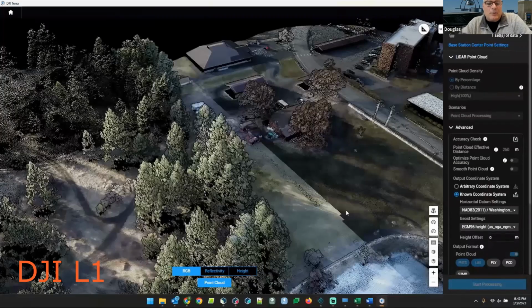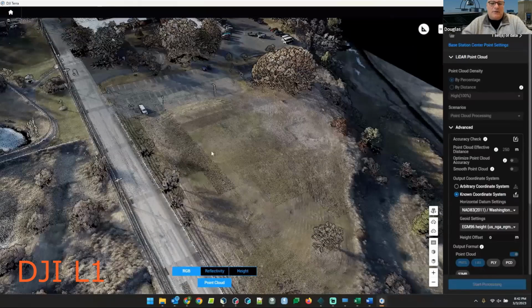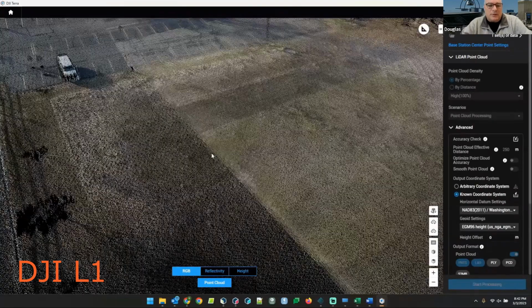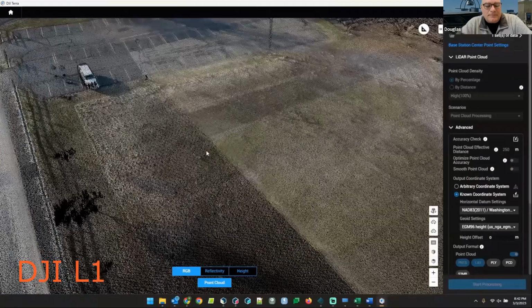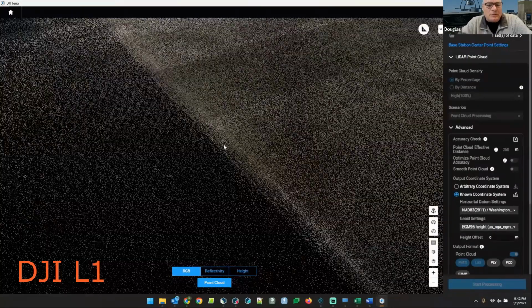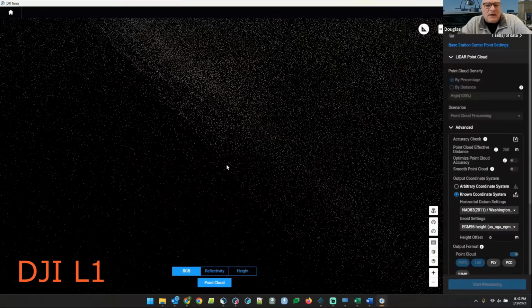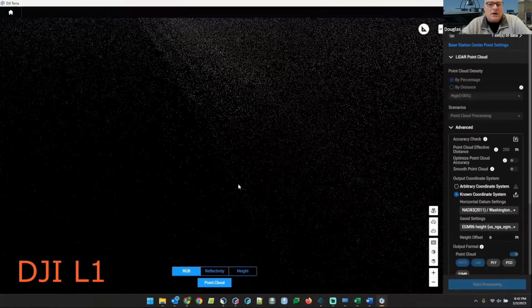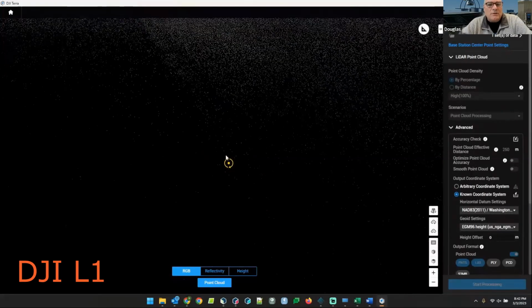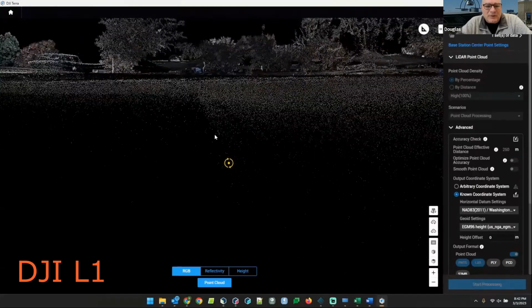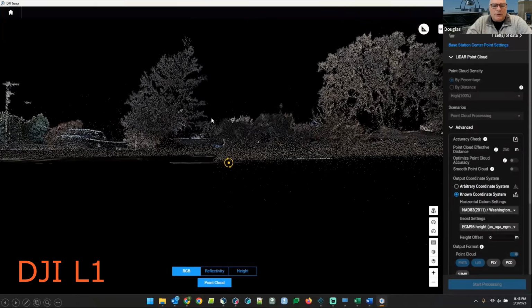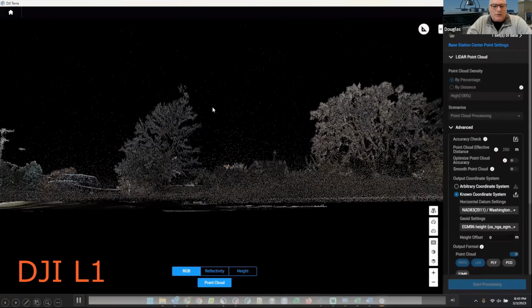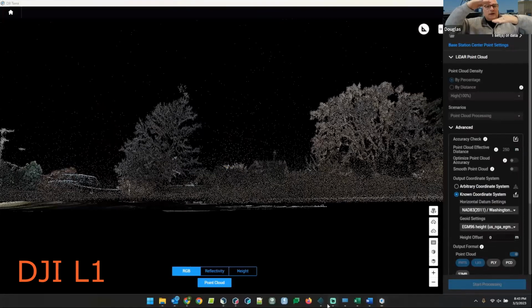So here's how that striping works. This is operating in DJI Terra here. And as we zoom in on those strips, so you can see where the strips are not aligned, let's zoom in very, very deeply. And when we zoom in deeply where those strips are, now let's flatten this out. And you'll notice that not only are the strips not properly aligned, but you'll see one strip is separated in strata from the other. So look at that. You can see down below here, there's one strip down below and another strip up above. In other words, they're not aligning the way that they need to align.